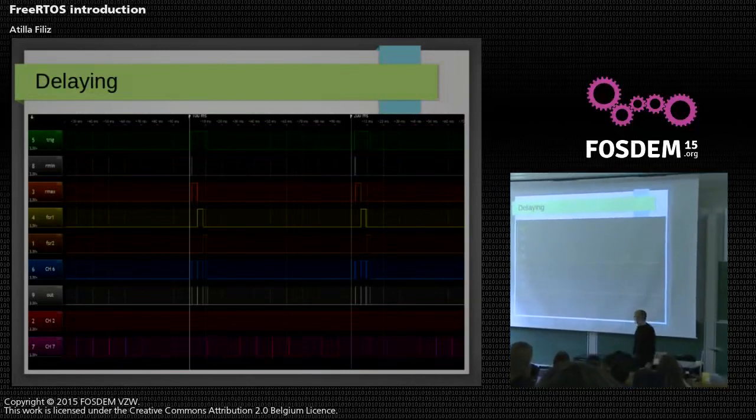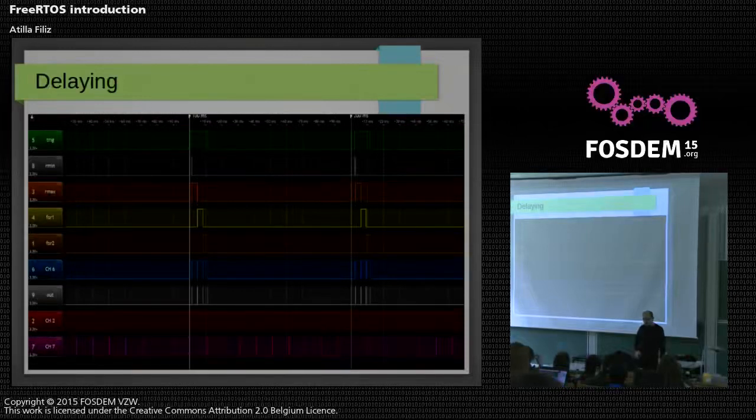So what I want to show you here is that whenever the green line is up, the CPU is busy with a high priority task. The switching of the purple function is delayed. It arrives late because it has a lower priority. But even if it misses some deadlines, the next deadline still stays periodic.